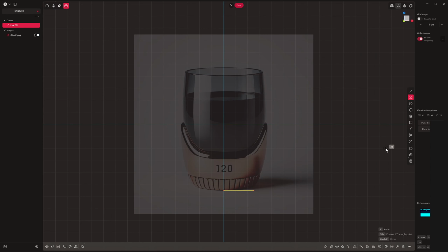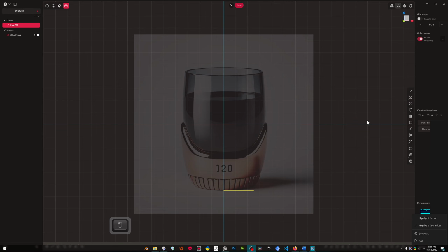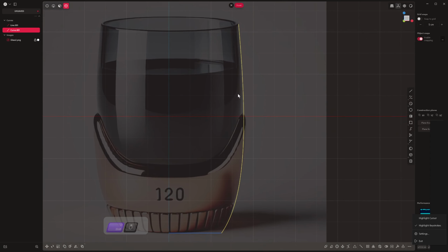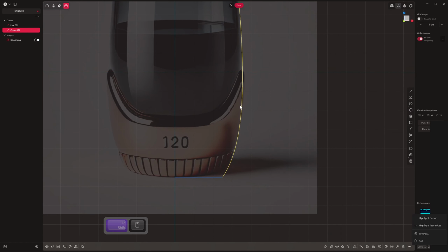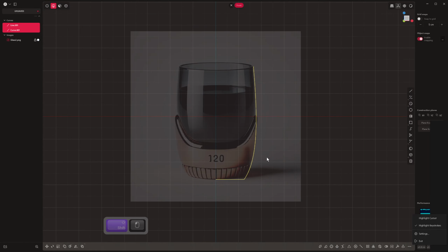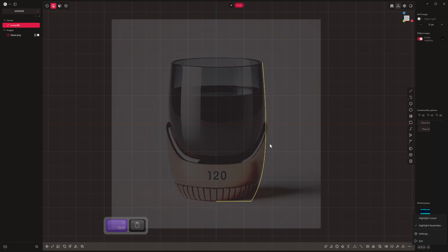Actually, let's quickly put on screencast keys. Alright, should have my keys showing up on the screen now. We're going to get this control point curve and we're just going to pull this out like this, and we're going to slowly get the shape, try and get that quite nice using as few points as possible. Okay, and now we can press number 2 and we can just join these two together by pressing J on the keyboard.